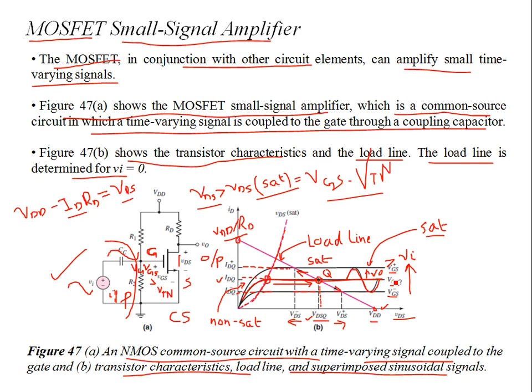So ID is basically over here independent of VDS. If you consider the DC quantities, then ID is given by Kn into VGS minus VTN, whole squared. VTN is a constant, Kn is a constant, so it's only VGS, but note over here that VGS is now sinusoidal. If you consider the AC quantity, small i with subscript D, then this is a small v with subscript GS.